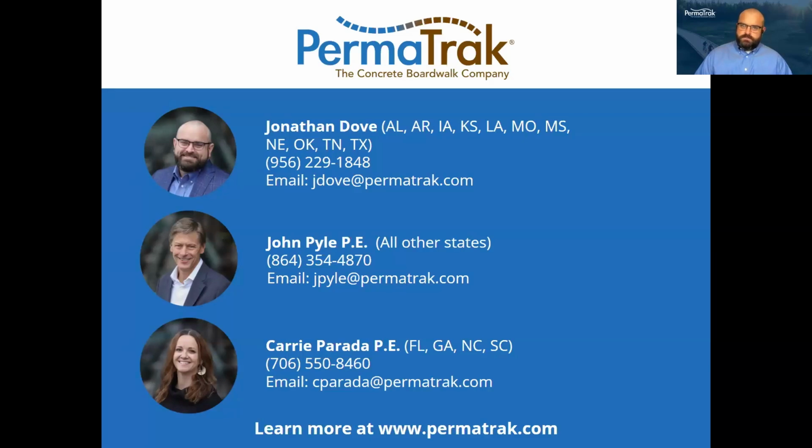Sure. Foundations in wetlands have largely been successfully done with helical piers. I'll give the credit to the helical pier industry there. They are small, they're light, they can be installed with light equipment. The sticks of the helical pier are 5-7 feet long. They can be advanced quite easily if the soil is suitable for it. But largely, a wetland is probably going to be softer soils, just by nature. So those work very well, and they can be installed from top-down construction.